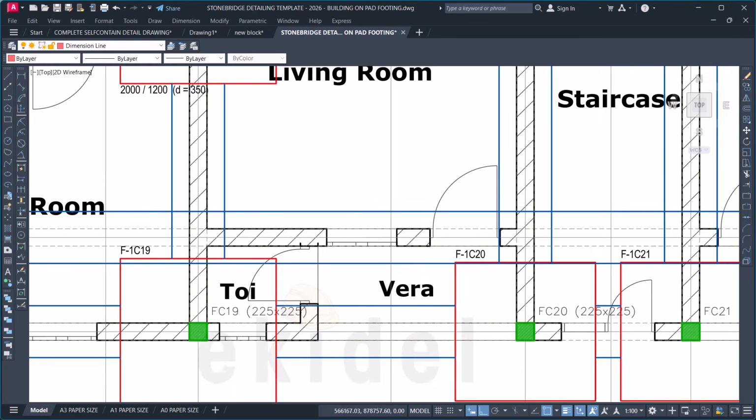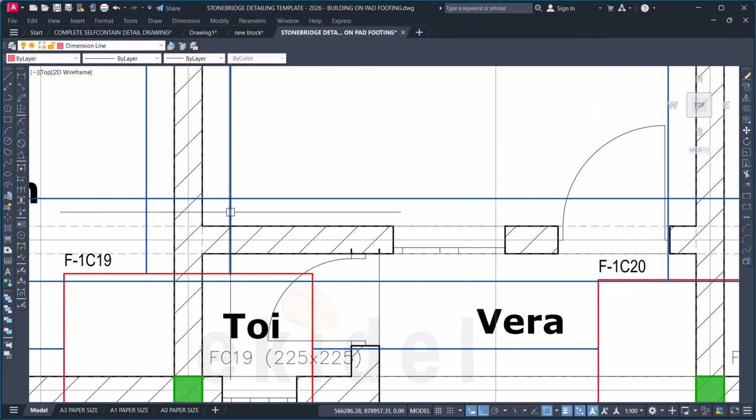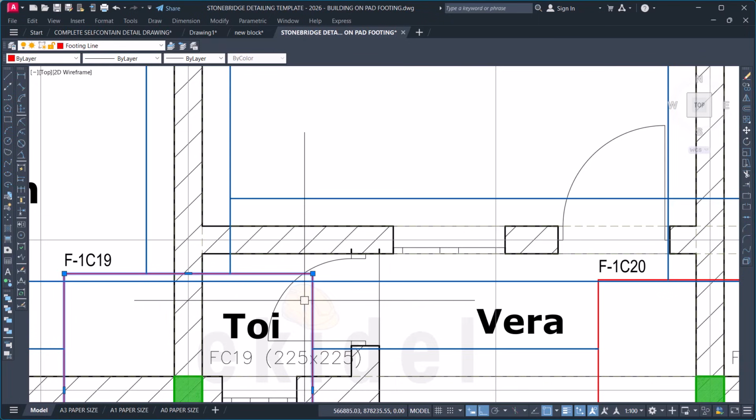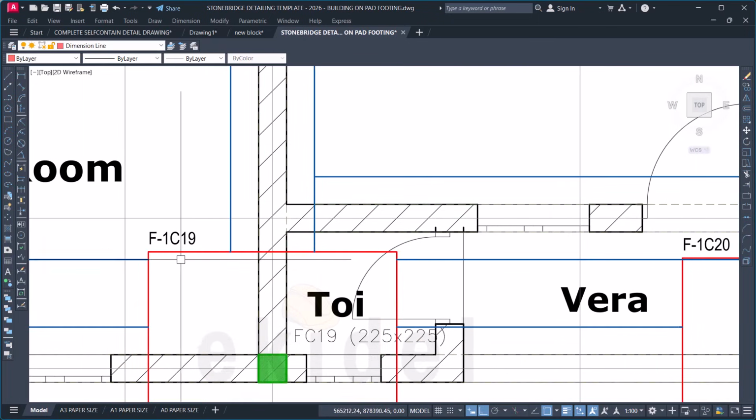And then this wall stops here. So what I will do, I'll click on this, TR, enter, trim off anything that passes this point, trim off this, and then let me see. Now I'll click on this and then trim off this. And I'll come now, click on this and enter.